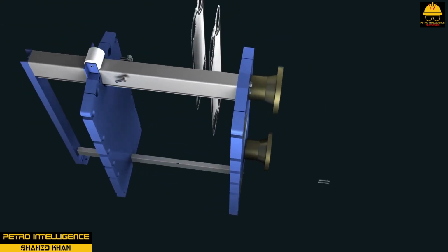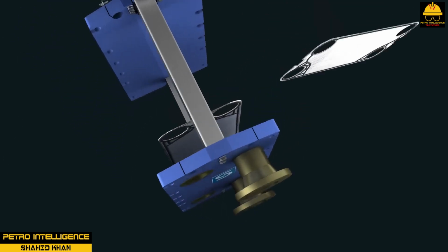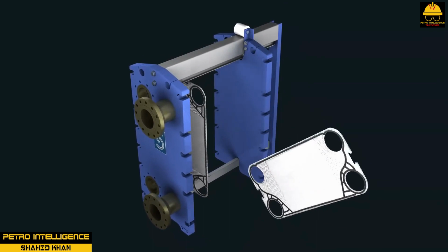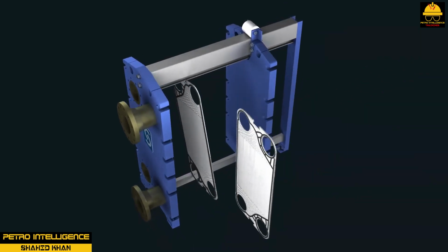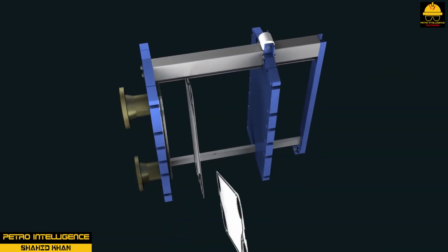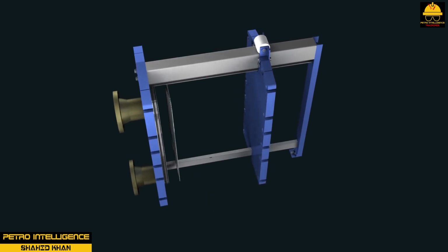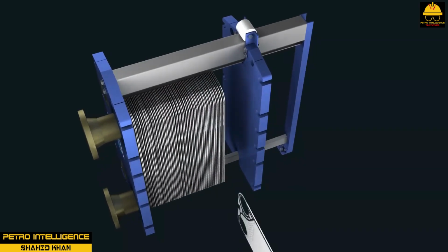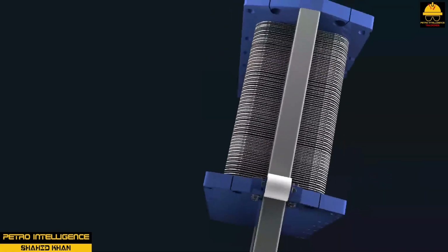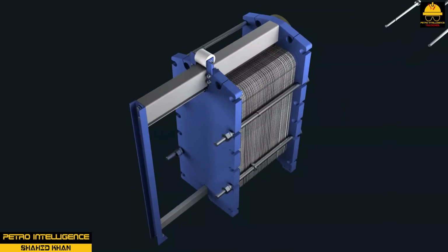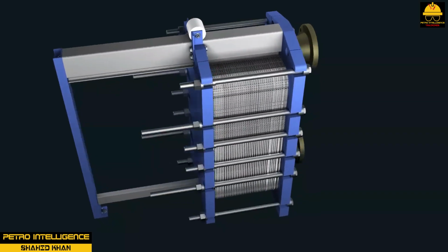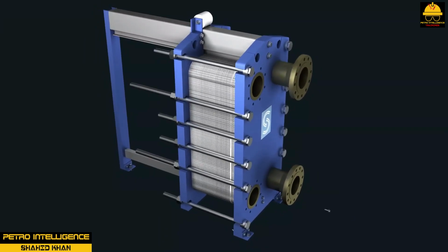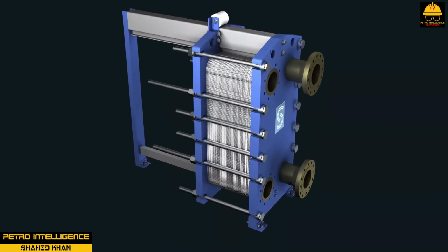can be achieved. The openings on the plate exchanger are located typically on one of the fixed end covers. As hot fluid enters the hot inlet port on the fixed end cover, it is directed into alternating plate sections by a common discharge header. The header runs the entire length of the upper plates. As cold fluid enters the countercurrent cold inlet port on the fixed end cover, it is directed into alternating plate sections. Cold fluid moves up the plates while hot fluid drops down across the plates.